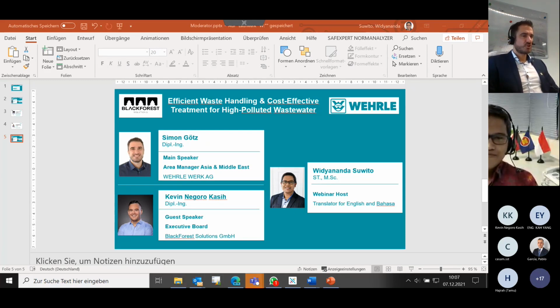Yeah, thank you. Good question, for sure. Direct leachate has high BOD and high biofouling, absolutely. What we are doing is we are using spiral wound elements which have a slightly bigger spacer. That bigger spacer inhibits too much fouling. Still, there will be fouling. Therefore, we have CIP cleaning, which we usually do, let's say, every 7th to 10th day.